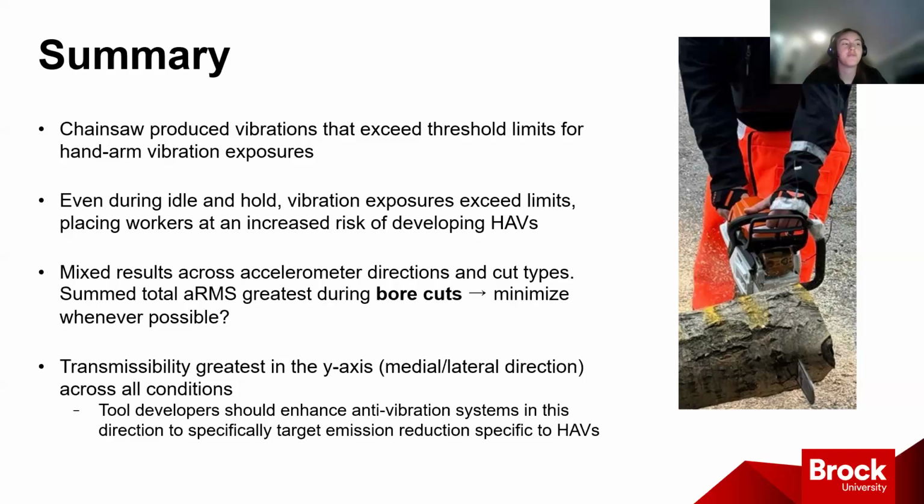So that's where I feel like these saw modifications are likely the way to go, rather than administrative controls. Typically, I really do think that the saw tends to be the problem and is kind of where we need to work on this, rather than at a worker level, where we can ensure that we're doing things like having proper neutral postures, controlling how hard we're gripping the saw, things like that, to reduce the vibration exposures. Changing the way that we're cutting, maybe not. I understand that they're job demands, and you can't really deviate too far from that. But the AV systems in the saw, I think, is probably the way to go to help mitigate these risks.